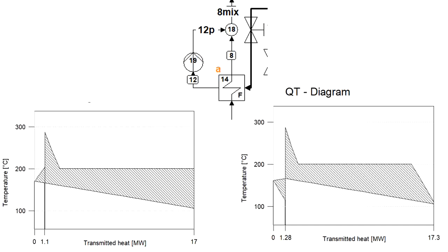On the other hand, on the right side of the graph, if we keep the minimum temperature difference of the heat exchanger at the cold side, the temperature of the condensate is actually colder than the temperature of the feedwater at node number 8, and after mixing the temperature would actually decrease, which would lower our system performance.